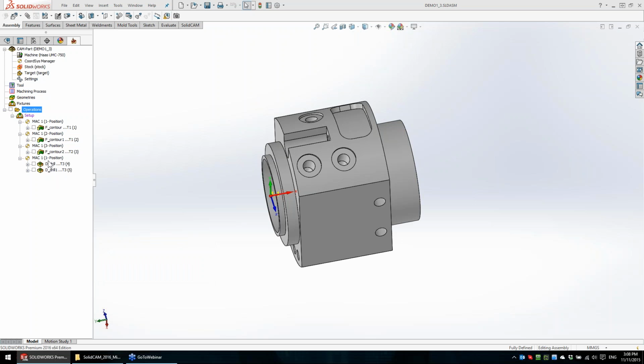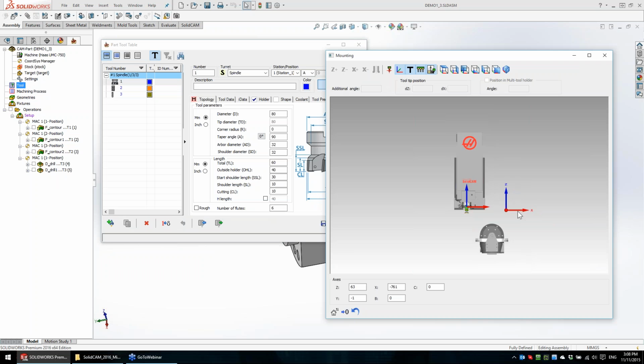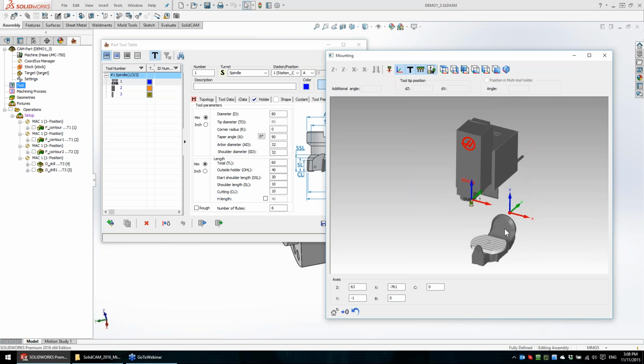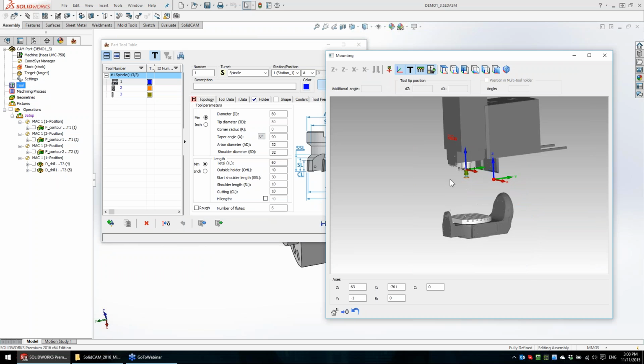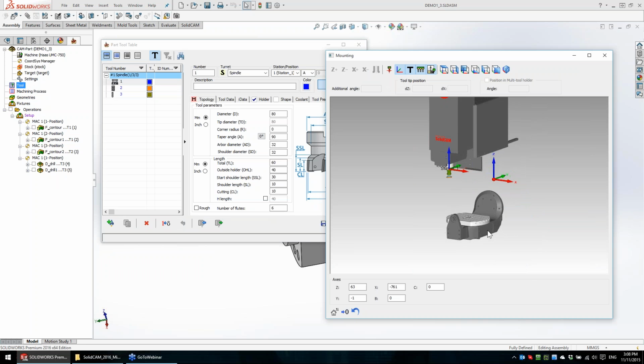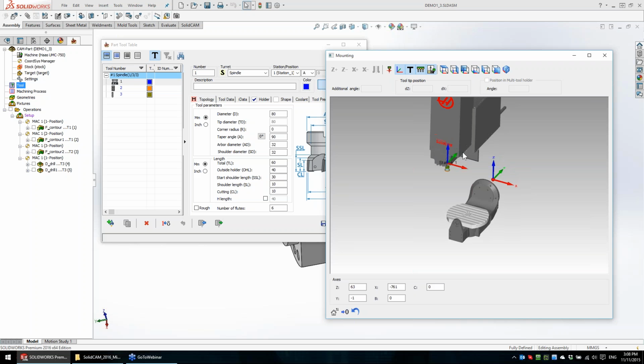I don't have anything wrong in operations. There are no red dot points alarming that something is wrong. Everything is okay. But if I go to the tool table, here is the machine. We show only the moving devices in this preview. You can see the entire machine in machine simulation. And here we have the spindle and the 5-axis device, the tilting and the rotating table.